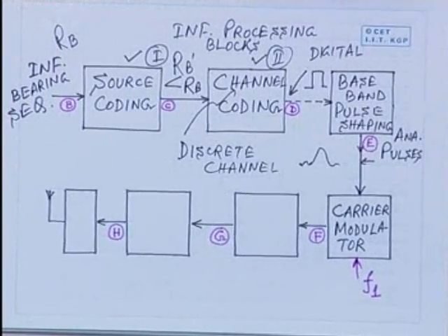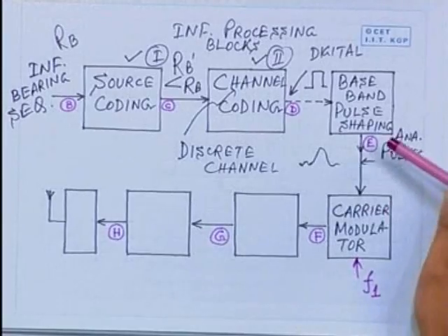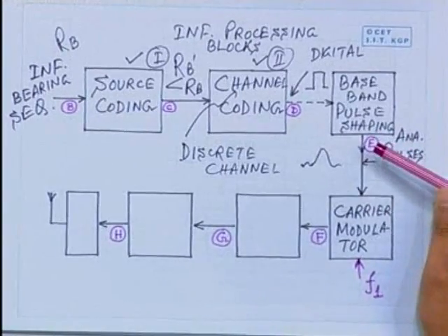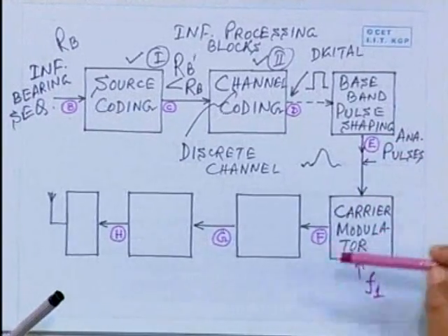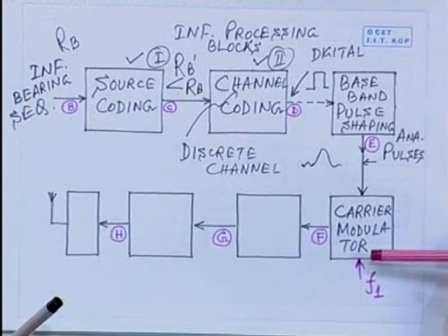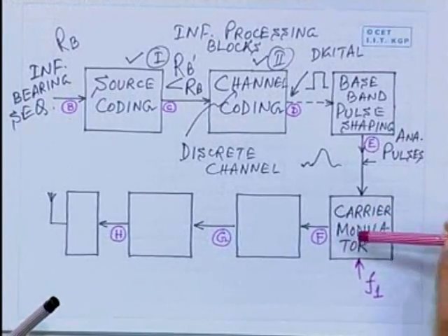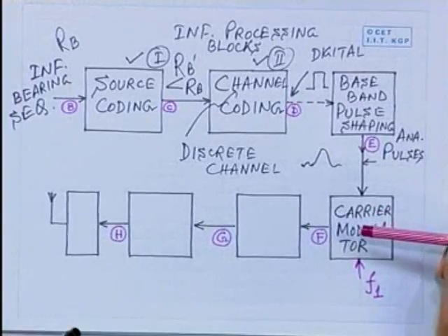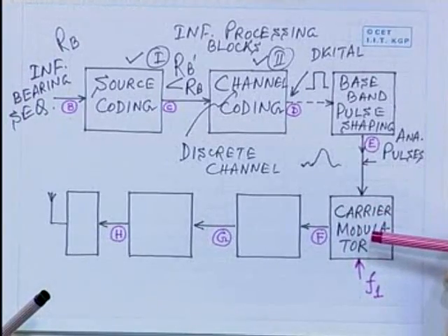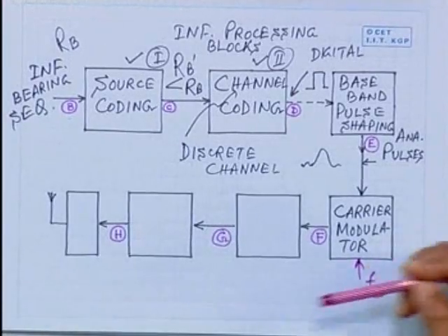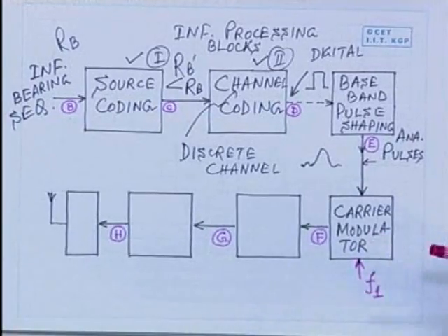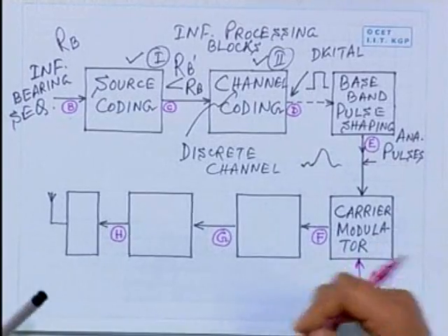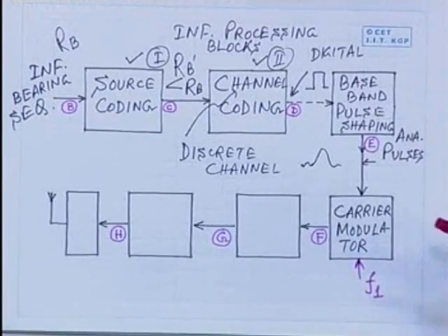There is some similarity, yes. If the modulation in the digital domain is in amplitude, it is somewhat similar to amplitude modulation. But we will see that there are many other interesting forms of digital modulation which are closer to phase or frequency modulation in the analog domain, and many suitable combinations thereof, amplitude as well as phase modulation and things like that. There are more digital modulation schemes to choose from, depending on what you have to satisfy and what kind of channels you have to use.